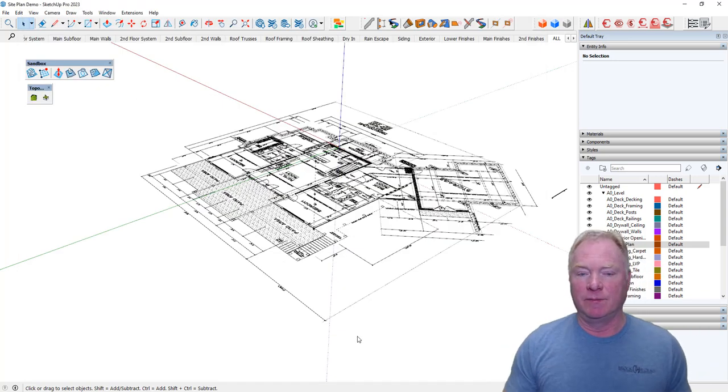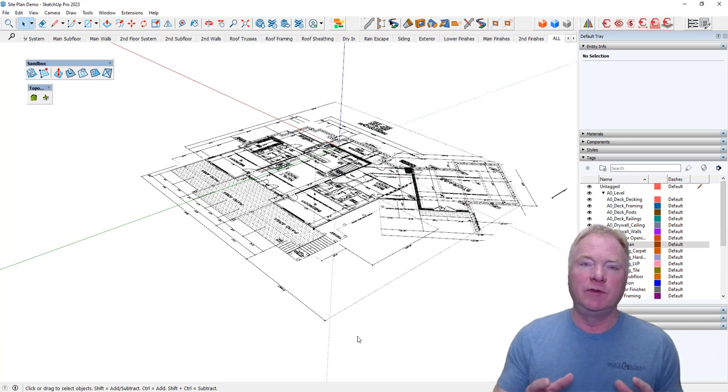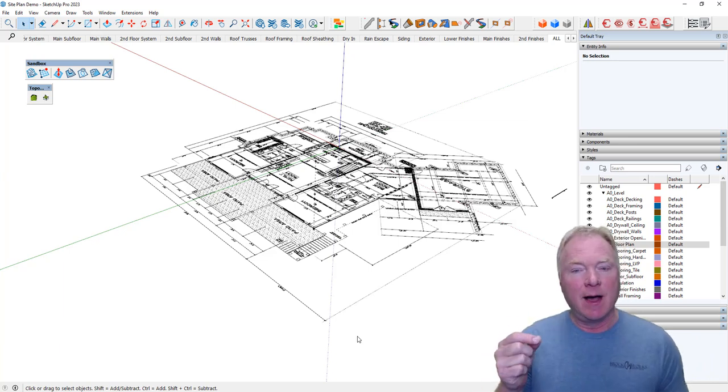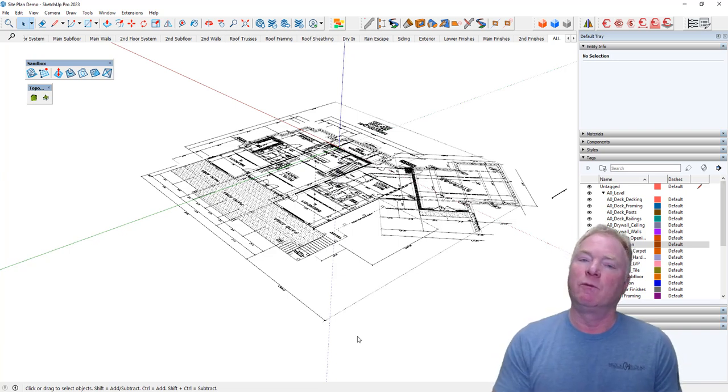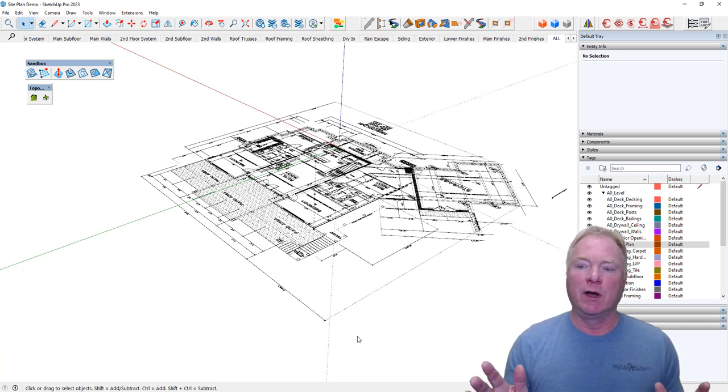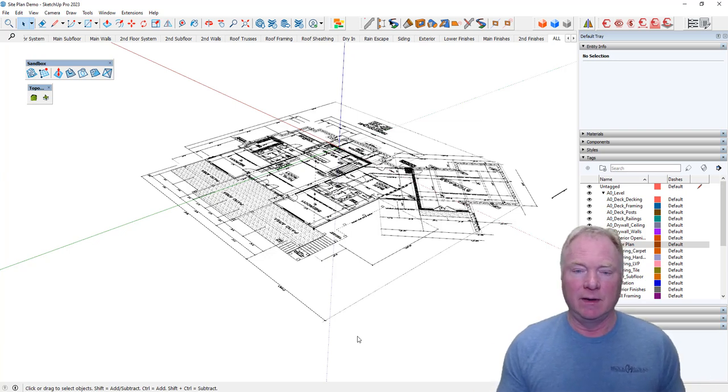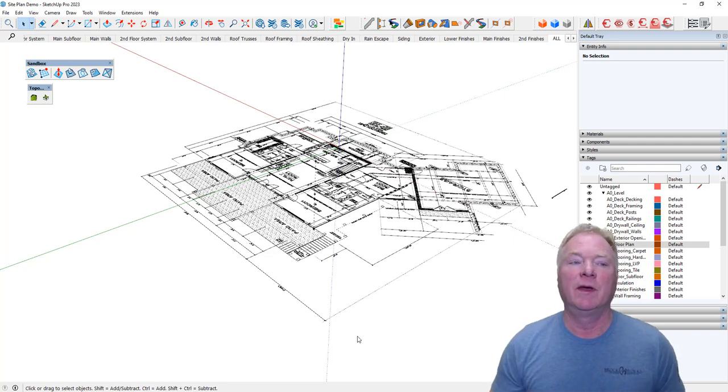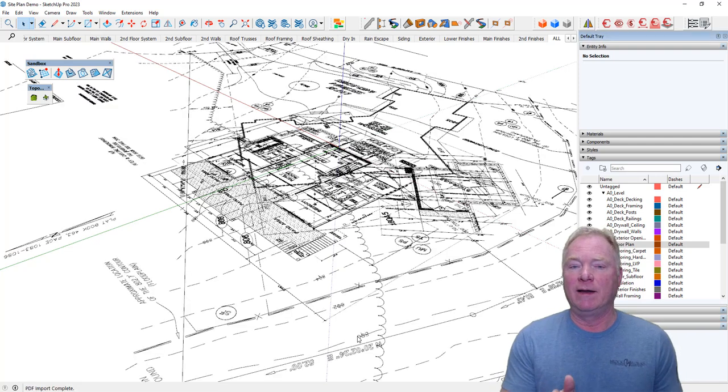Once that comes in, we're going to find that same common stacked point, and we're going to move it over, but then we have to rotate it to align it. So remember, we're going to rotate the site to fit the house, not the other way around. You want to keep everything in those red and green axes. We're also going to get north out of this.